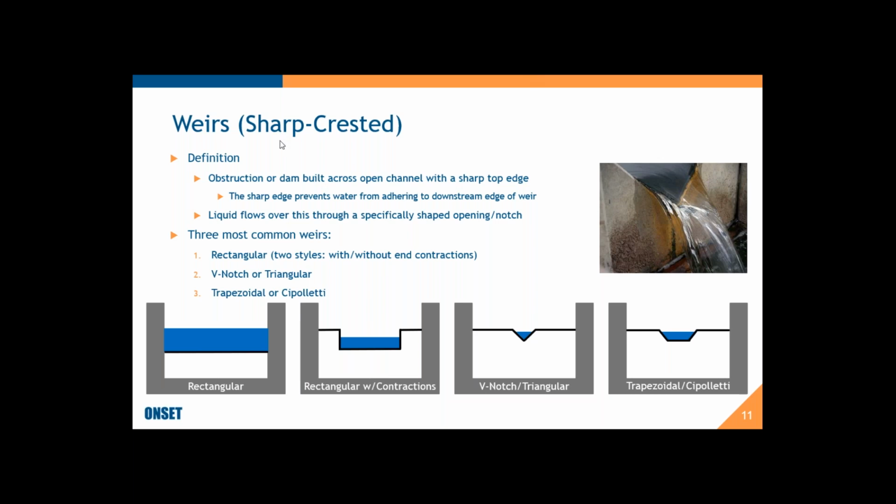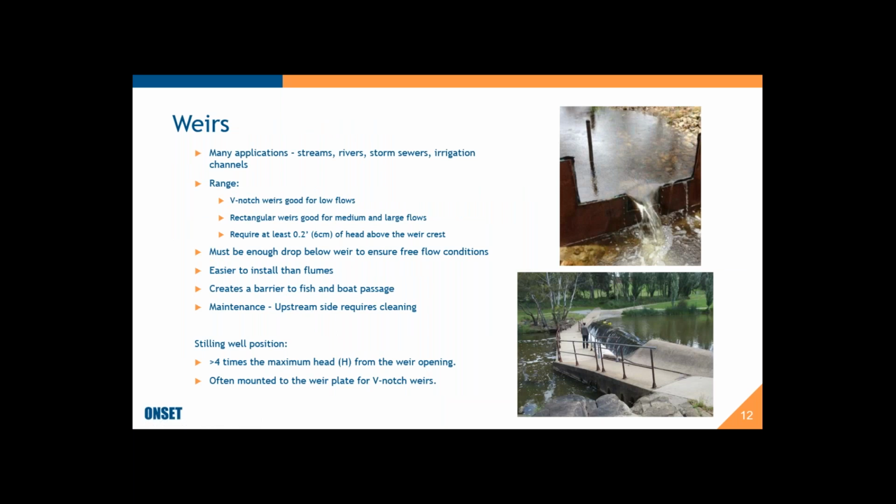And there's also hybrids where you can take a V-notch weir and combine it with a rectangular weir to better adapt to different types. As a matter of fact, here's a combination weir that has a V-notch weir down here and then a rectangular weir up here. So to really characterize a flow like this, you need to have two parts of your equation, or your conversion.